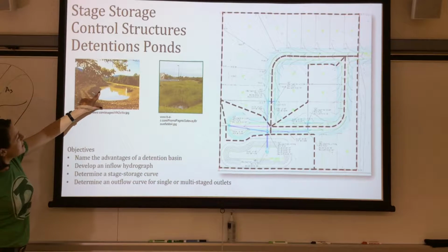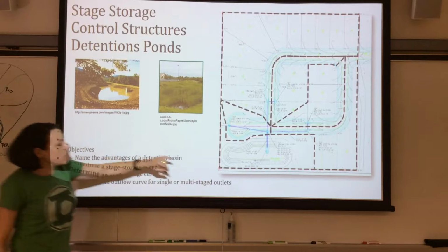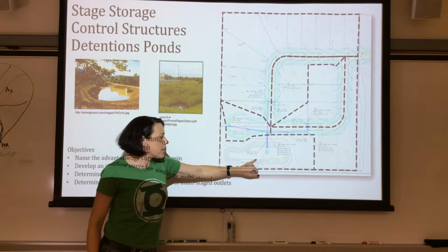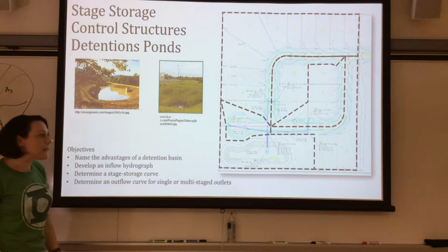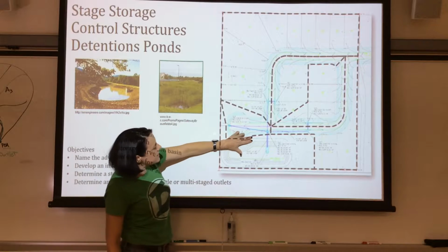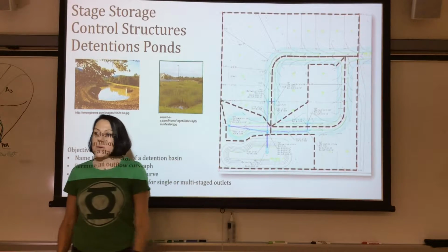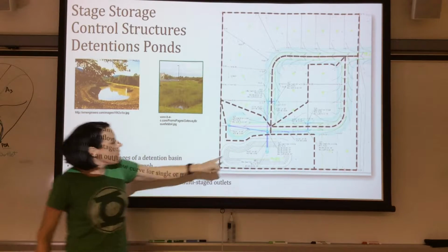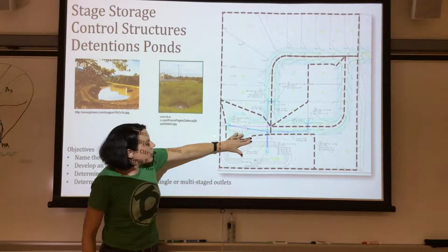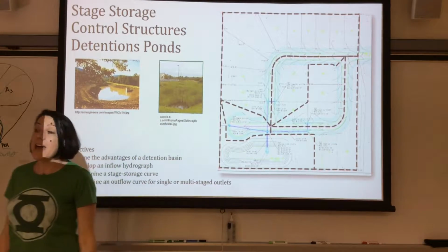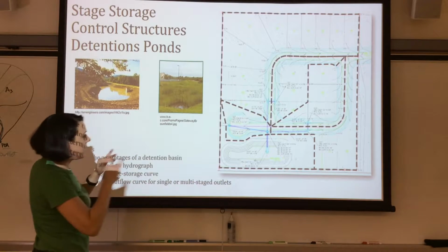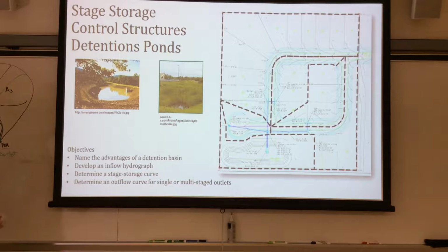So it's the elevation change. If you were looking at this, this water surface would be this last contour right here, this last line that's shaded a little bit green. And the top here where it's kind of flat, notice that there's a flat area in between, a space that's much different. So the distance between this line and that line is 4 feet. The difference between these two lines is usually 10 feet, sometimes 20. But normally top of bank is sloped at a 10 to 1.